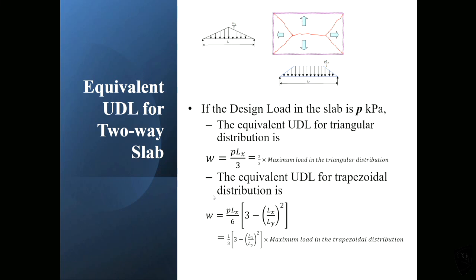You can use this one, and we discussed this last week. But for the slab design we don't need to change to the equivalent load. For the beam design we need to. So that's basically the slab design.